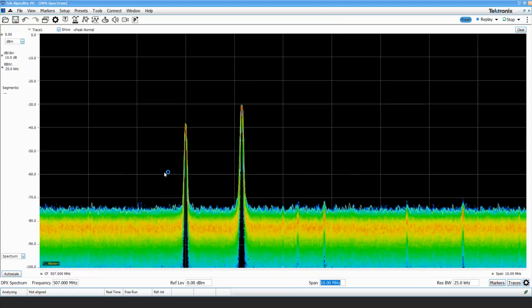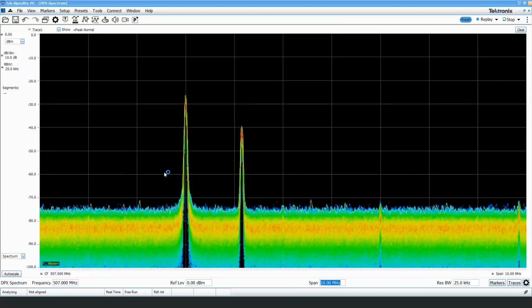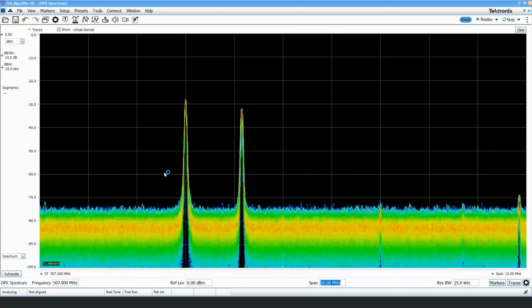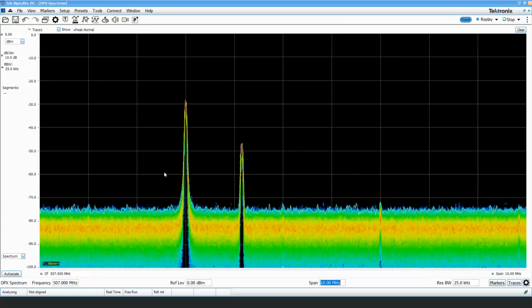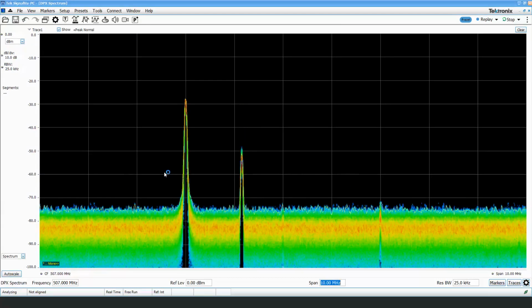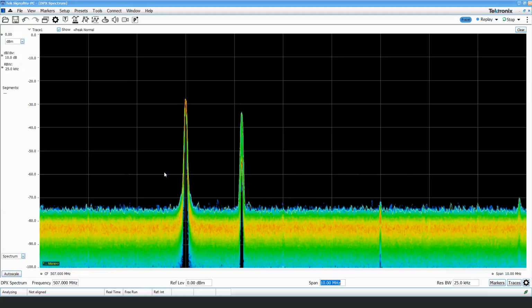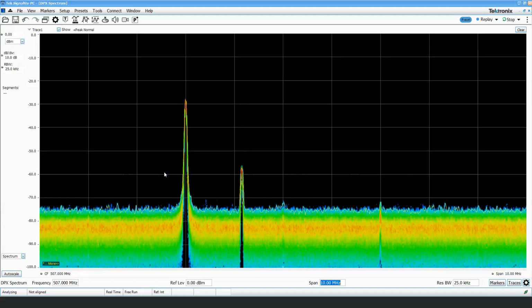The other thing with that is if you reduce your power in campus type scenarios, you're also not bleeding through walls. Since these are UHF microphones and lower frequencies, it won't bleed through the wall and impact neighboring spaces quite as much. So a good practice is to take your transmitter, walk the room, cover the antenna, and see how far you can walk and get it to the lowest possible power.